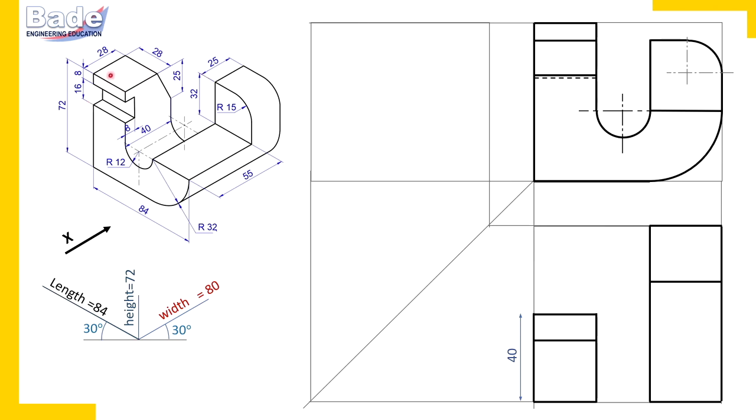So here it is: horizontal surface and then inclined surface, which is visible from top. Now let's proceed. Semicircular slot. Its opening is a semicircle, or you can say this semi-cylindrical surface. In front view, it shows its semicircular shape. So of course, in the top view, it is a rectangle, and in the side view also it is a rectangle. Let's complete the top view.